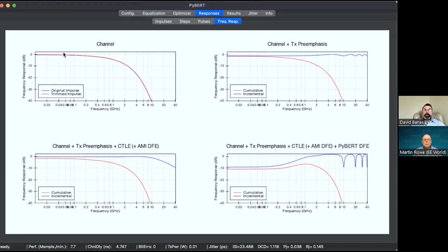And as you can see, just as you predicted, Martin, it rolls off as we climb in frequency, just like a low pass filter would. And that is, in fact, what causes the distortion in the signal at the far end. And so what we're doing with equalization is we're basically just trying to counteract that high frequency roll off. And we do that by applying blocks or system modification components that actually have higher response in the high frequencies.